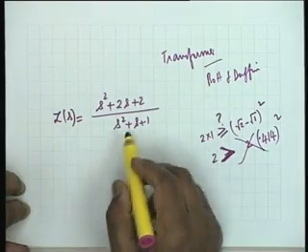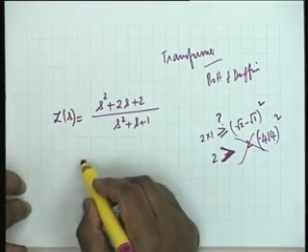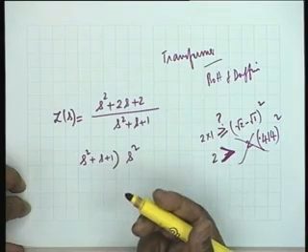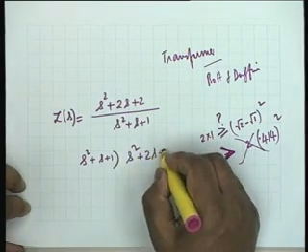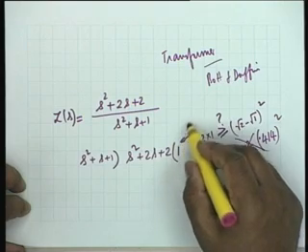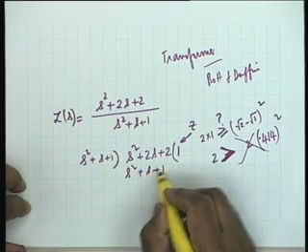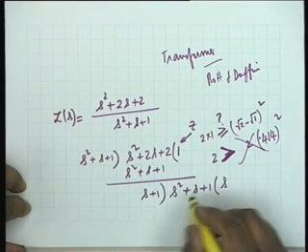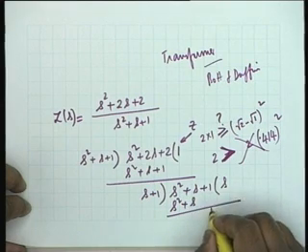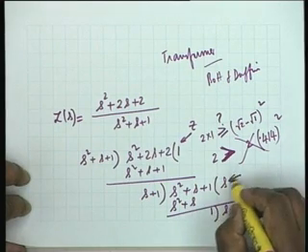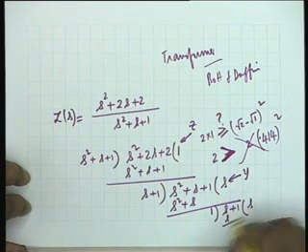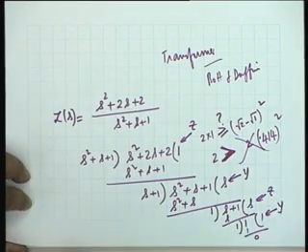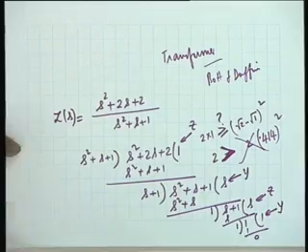But you see, if you make a continued fraction expansion, let us see if it works. s squared plus s plus 1 blindly. I mean, I don't know how else I could do it. So we try continued fraction. s squared plus 2s plus 2 divided by s squared plus s plus 1, this is an impedance. I am left with s plus 1, which divides s squared plus s plus 1: s squared plus s, then 1, s plus 1, and then 0. This is impedance and this is admittance. So, it does work. We have got all quotients which have real and positive